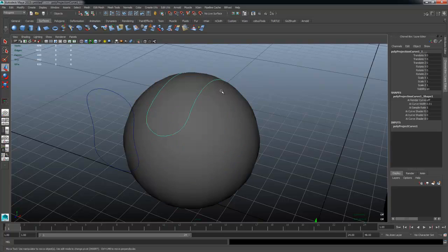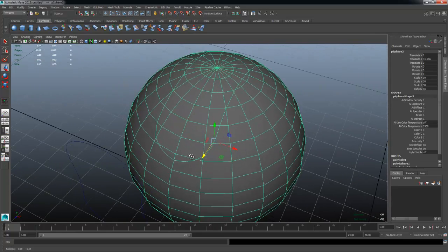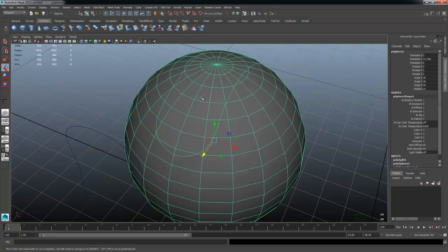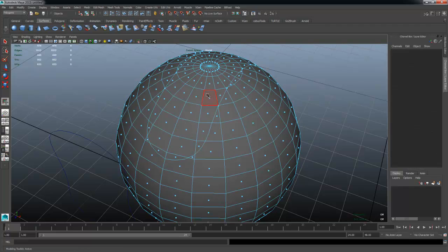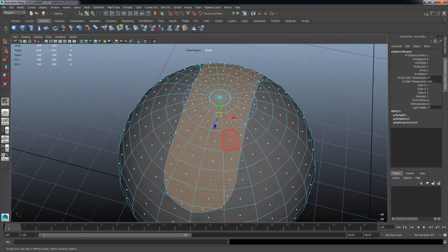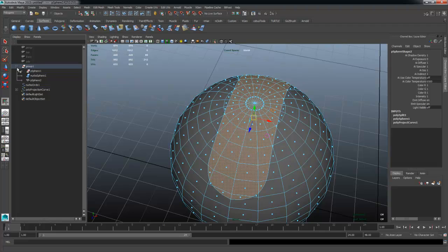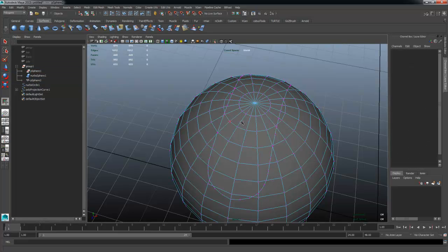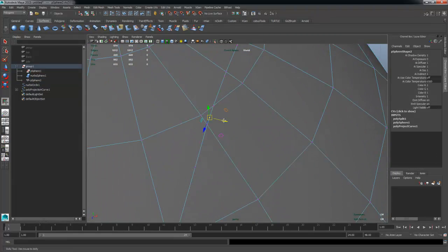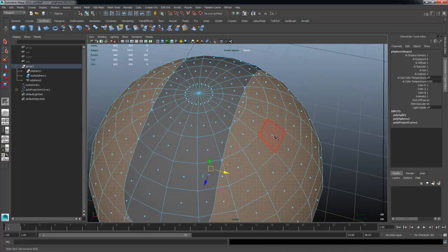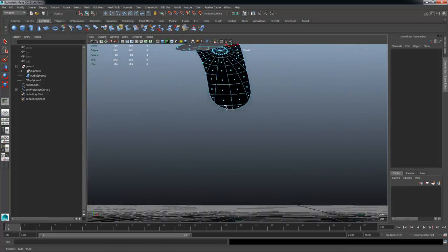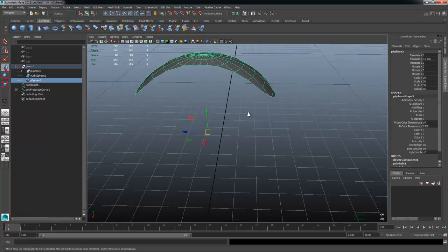And we're back. So the final projection ended up being successful with now these two meshes being detached. Now, detached does not mean it is physically extracted. It only means that these components are now two separate divisions inside of the actual model. If you just open up this, you'll see that it's still one sphere, but the vertices are now completely separated from each other. So now it's a completely open model. This is great if I want to quickly select the outside and press delete, and that's going to give me the final result on the projected model.